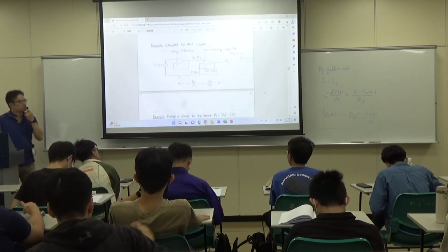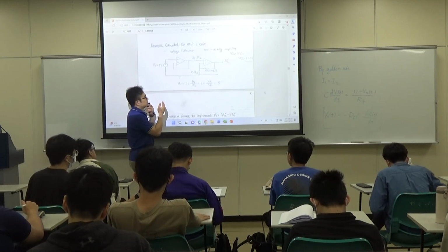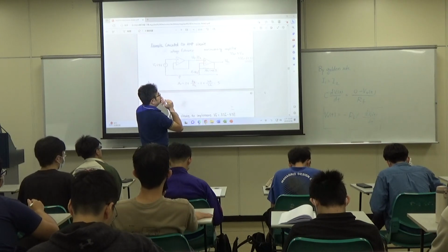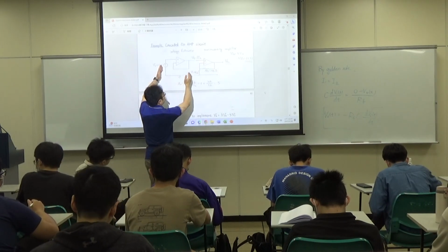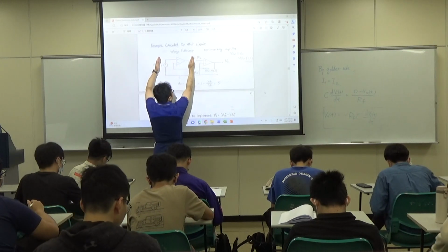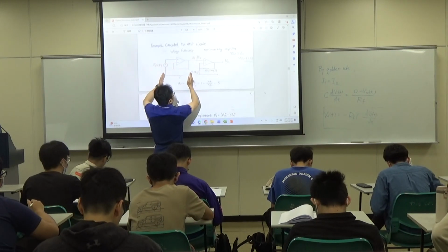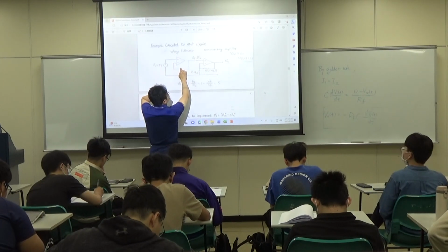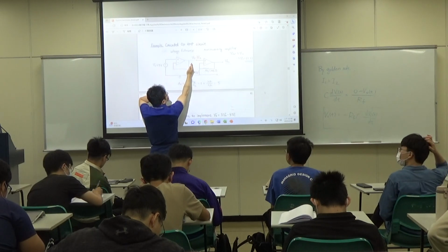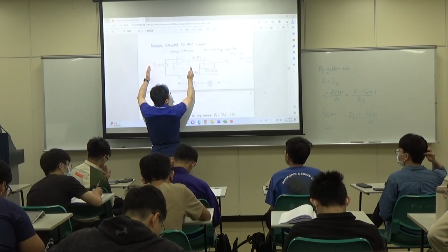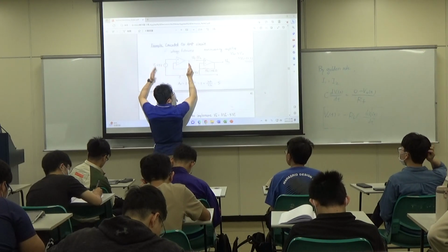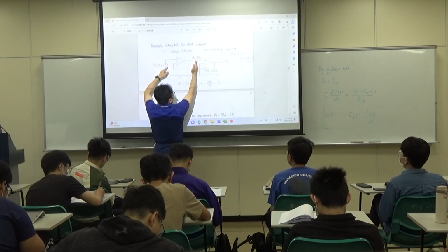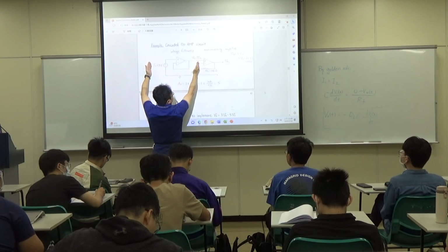So this one is simple because I already wrote it down. You can see they are independent, because of the characteristic of the operational amplifier: it has a very large input impedance, so you can calculate each one independently. This first one is a buffer. We also call a buffer a voltage follower. If you know the structure, you can immediately know it's a buffer. If you don't, you just look at this operational amplifier only, and you can derive it by using the golden rule.